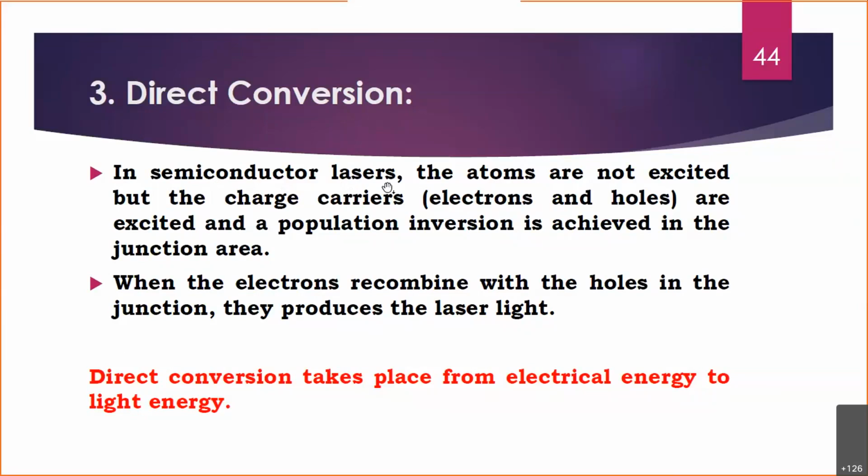Okay, and what happens in this is that atoms are not excited, but the charge carriers like electrons and holes are excited, and then an inversion is achieved. So this pumping is required when the energy levels are very nearby. I mean, the energy level difference has to be very small. So this kind of pumping is useful in such a scenario because it is not exciting the atoms themselves, but it is exciting the charge carriers like electrons and holes, because it's a semiconductor.